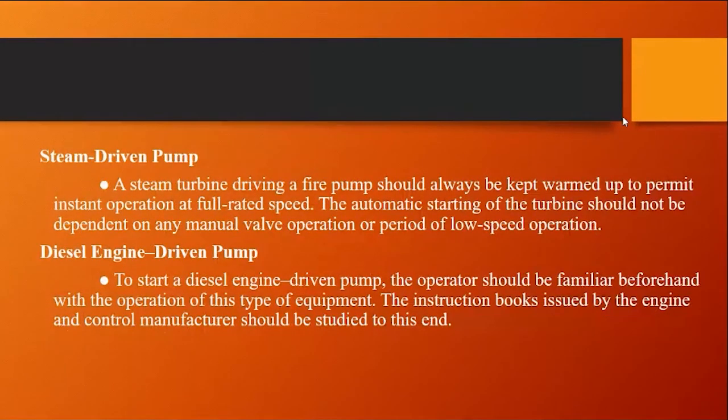Steam driven pump. A steam turbine driving a fire pump should always be kept warm to permit instant operation at full rated speed. Automatic starting of the turbine should not be dependent on any manual valve operation or period of low speed operation. Next is the diesel engine driven pump. To start a diesel engine driven pump, the operator should be familiar beforehand with the operation of this type of equipment. The instruction books issued by the engine and control manufacturer should be studied to this end.